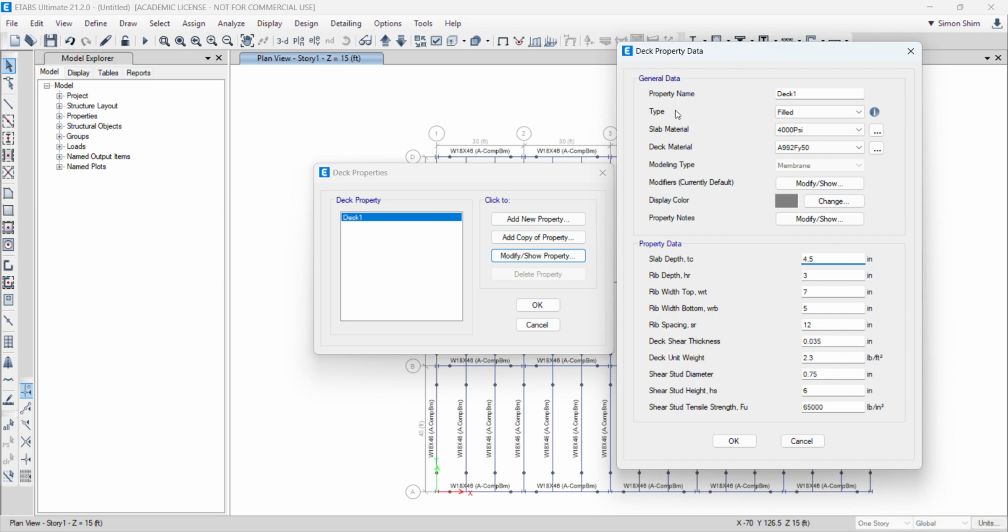Now, the most important thing is the naming convention. If you are managing maybe an entire 40-story building, with all the section properties and material properties, come up with a very short name with a prefix. Otherwise, you're going to end up with a very long name. Sometimes software like ETABS, or Windows, doesn't recognize a long name. I remember there was a limitation on the number of characters.